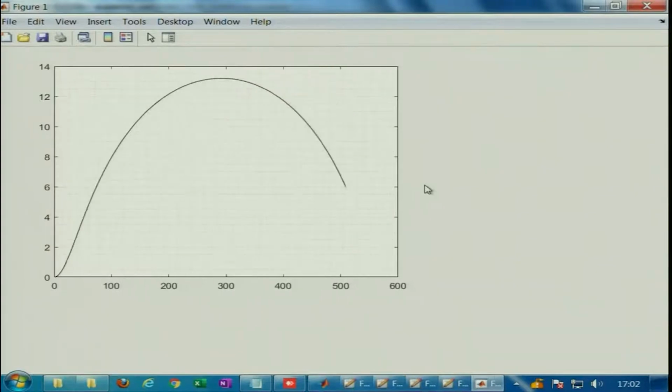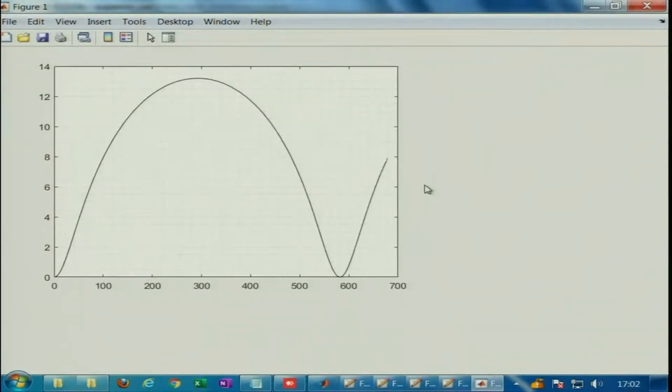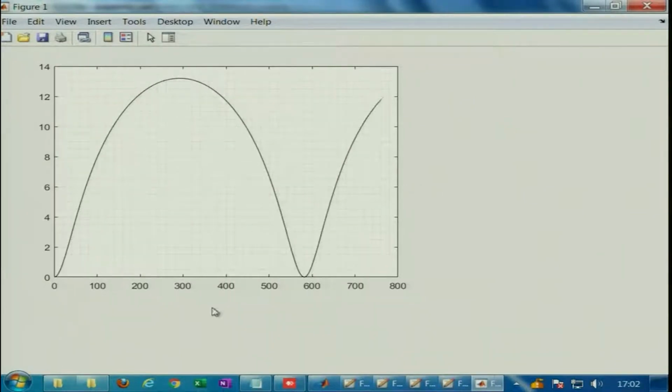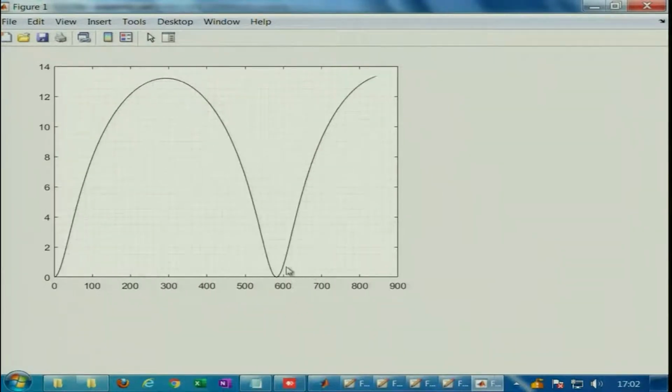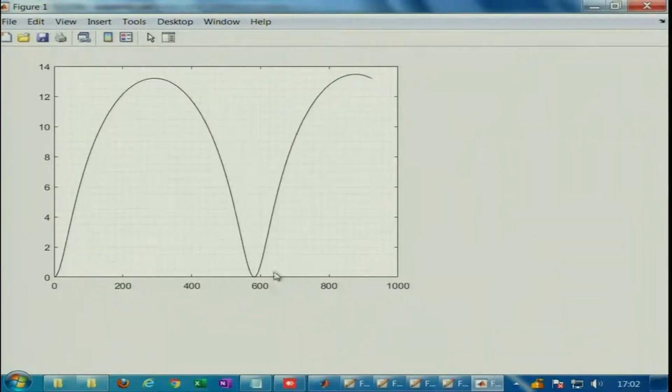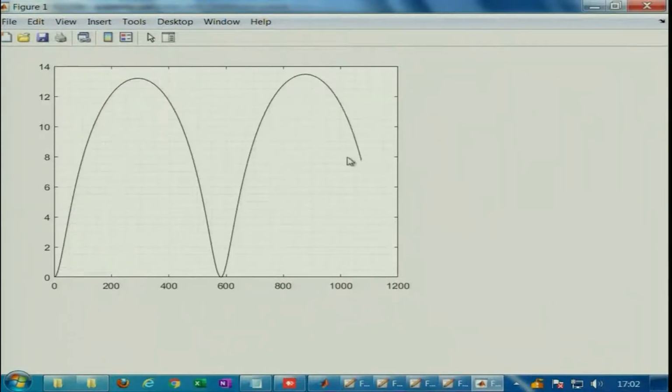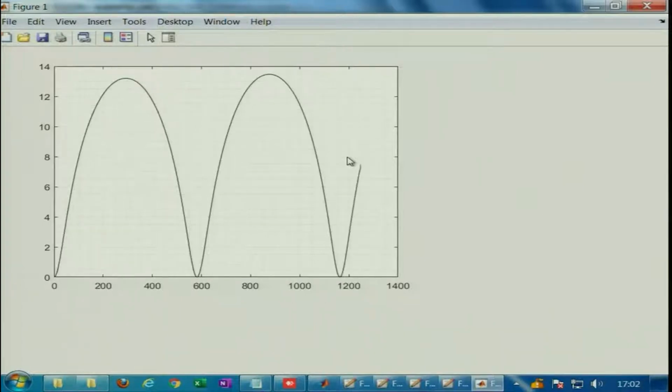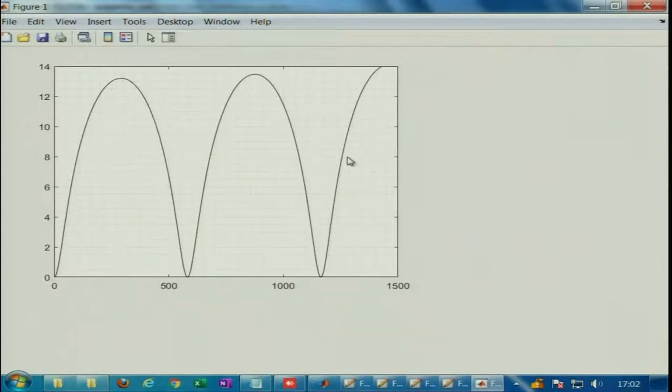So, you should be really getting, for the 300 length and 346 speed, a trough here at 577 hertz, and a peak is based on, again, the expansion ratio. We will work out all these things. Let it first compute, and after a while now the 3D effects will start to kick in. Probably I should have considered a higher frequency range.